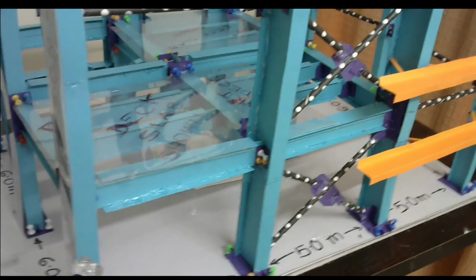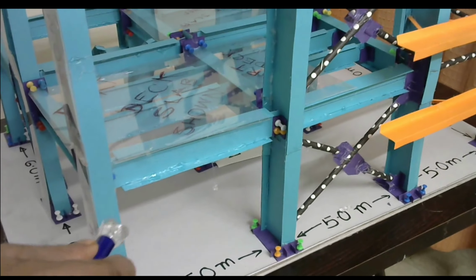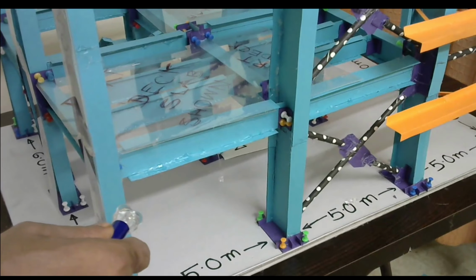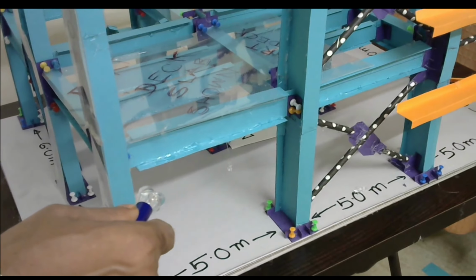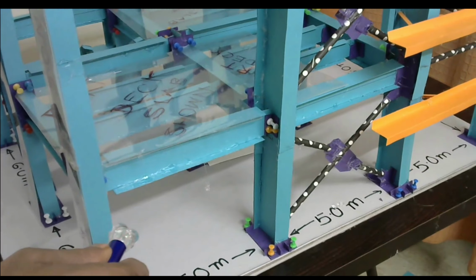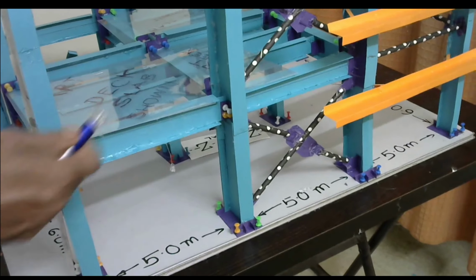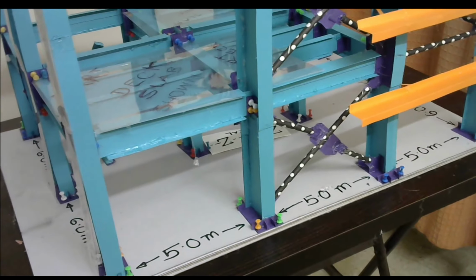See, in LX parameter, the code says the torsional resistance can be at any level. It need not be near the compression flange. But obviously for the LY parameter it should be near the compression flange. So for this, the LX and LY we can take as the screw spacing. Screw spacing is usually double the corrugation of the deck sheet.